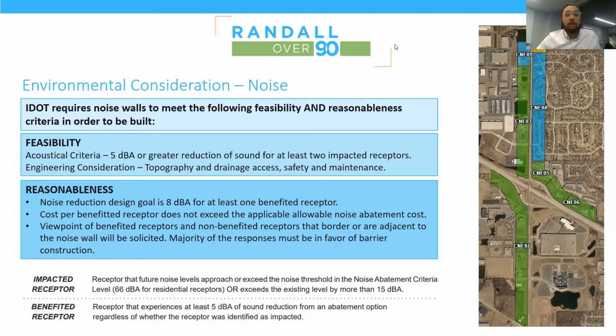What does CNE04 mean? Good question. CNE means common noise environment, and CNEs are grouped with receptors of similar land use and similar exposure to the roadway. So you can see there CNE01 and CNE04 are blue because they're residential, and residential CNEs have a specific noise abatement criteria for residences.